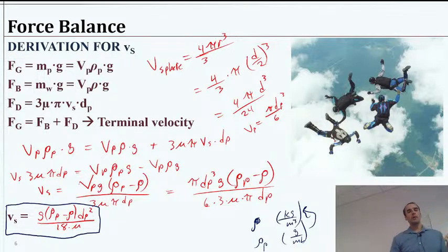One thing we could think about, before we even talk about designing a reactor, because that's what we'll talk about today and in the next lectures, is how to improve sedimentation. We look at how to improve this number, how fast these particles are falling through the water. That's going to tell us a lot about how big of a reactor we need, and what kind of particles we can remove.